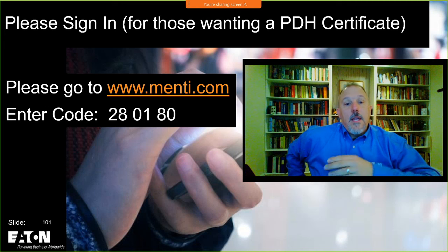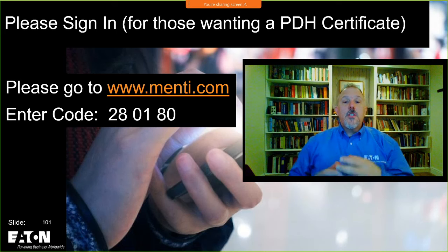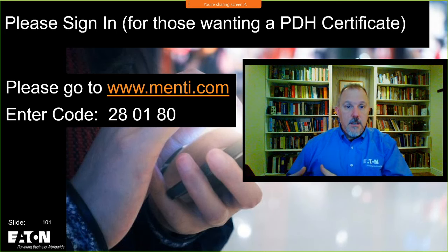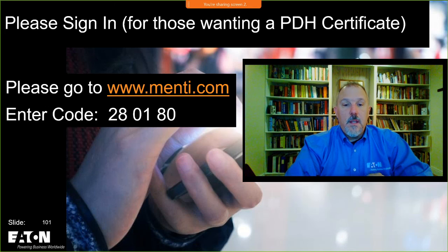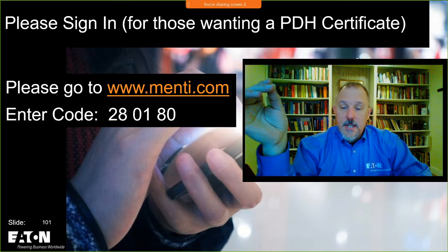From a compliance perspective, whatever the solution there is that's meeting the 210.8(B) requirements, they have to be listed. That's why the standards are very important. If it's listed as a GFCI solution, then you could argue it is meeting the requirements of 210.8(B)(2). I agree with you, it doesn't sound like it is meeting that requirement, but you would have to ask for, show me what it's listed for, get the label off the equipment. If it's listed as a GFCI, then it would meet the requirements for 210.8(B). If it's not listed as a GFCI, it will not meet the requirement. One issue, though: we are understanding that there are no three-phase GFCI receptacles. Right, there's no GFCI receptacle.